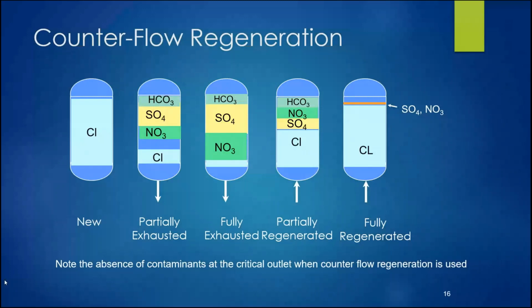If you have a high purity application, you want low leakage of contaminants into your downstream DI water. In the counterflow method, the bottom of the resin bed is fully regenerated and able to produce the highest purity water. For comparison purposes, where absolute pure water has a resistivity of 18.2 megaohm, only counterflow regenerated mixed bed systems can offer the lowest leakage rates to deliver ultra high purity water of 17 plus megaohm resistivity. A good two-bed countercurrent regenerated system can produce 15 plus megaohm resistivity, while a two-bed co-flow system would only produce a 10 plus megaohm resistivity.